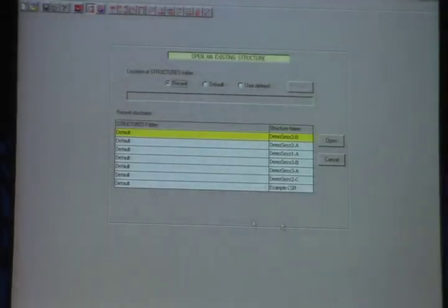So I did a third analysis here, and what I did was I took the beams and I put in axial releases in the beams, so that even though they were restrained by the rigid floor diaphragm, they could have zero axial force because they had an axial release. And I'll do that with looking at a third model.